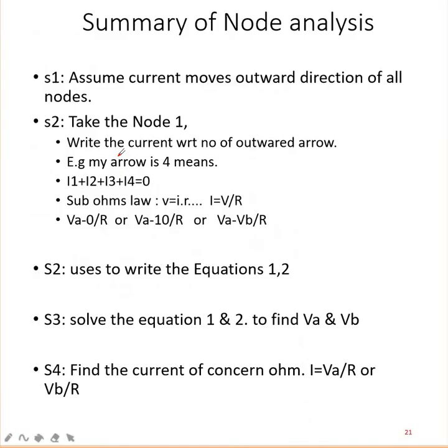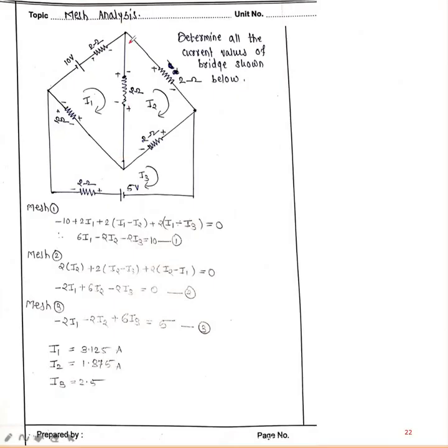Okay, so summary. Mesh analysis is similar to Kirchhoff's voltage law. Assume your own directions and write the equations. Equation numbers 1, 2, 3 for I1, I2, I3, you will write. It is similar to Kirchhoff's voltage law, no changes.